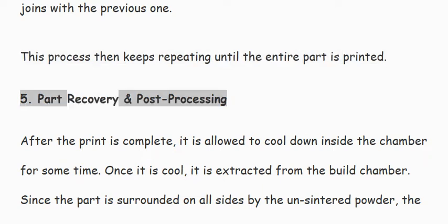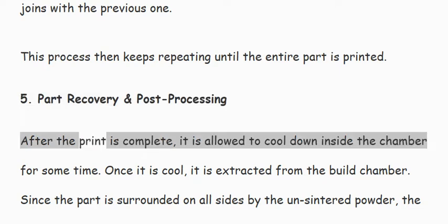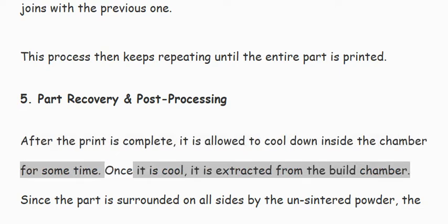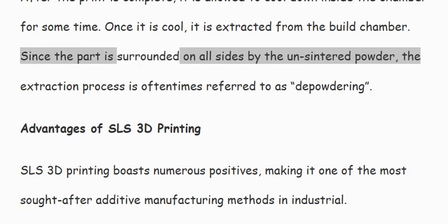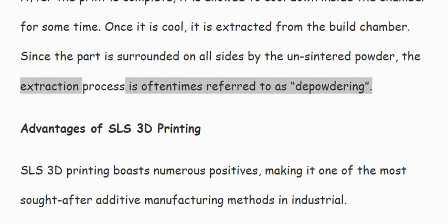5. Part recovery and post-processing. After the print is complete, it is allowed to cool down inside the chamber for some time. Once it is cool, it is extracted from the build chamber. Since the part is surrounded on all sides by the unsintered powder, the extraction process is oftentimes referred to as depowdering.